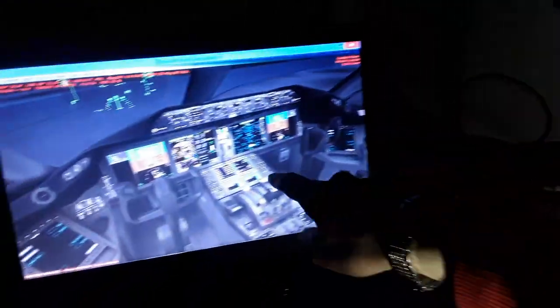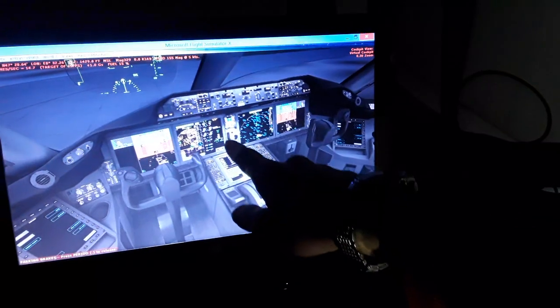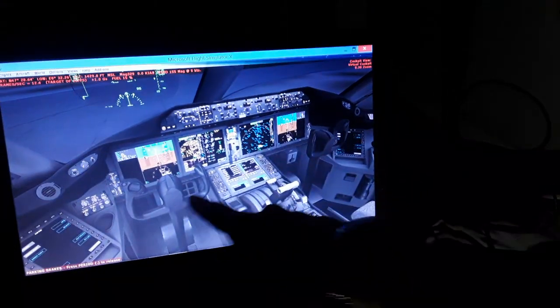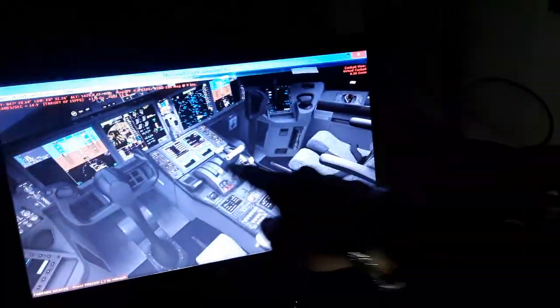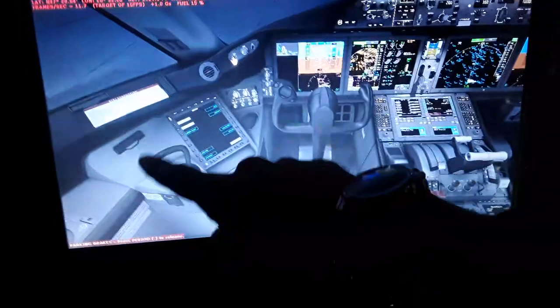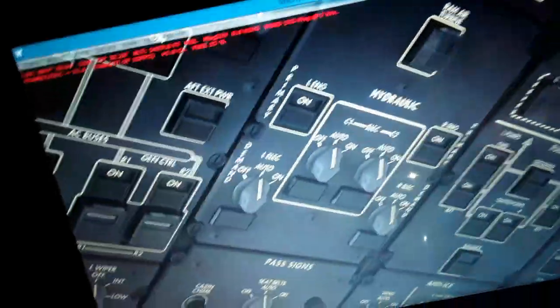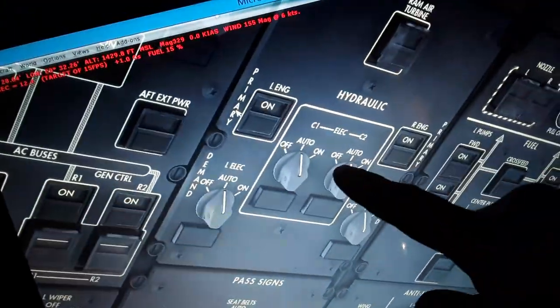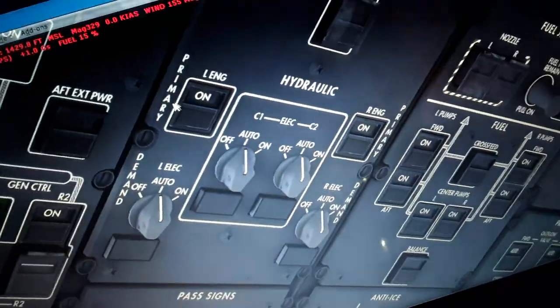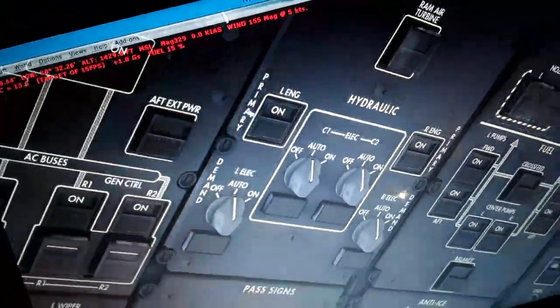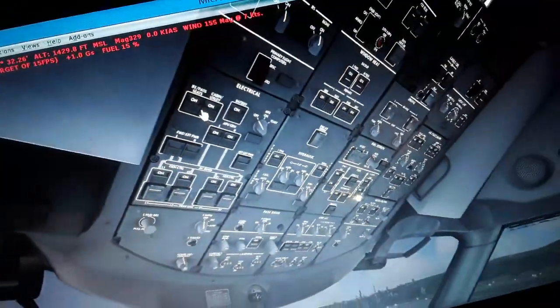You see here the thrust reversers for the engine, landing gear, extender, retract, auto brakes, parking brakes, rudder over here, flaps and slots, speed brakes, nose wheel steering over here, the tiller. We need hydraulic fluid over here, pressure, demand over here, and primary, electric driving. All are pressurized. All tanks are pressurized hydraulic tanks. We serve from the engines.